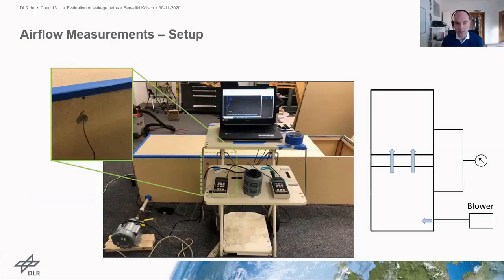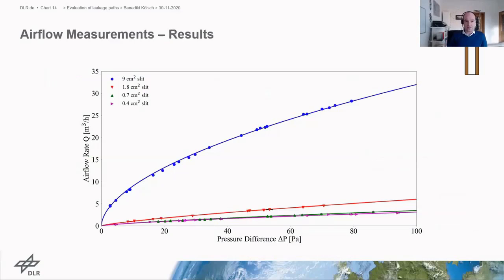And therefore, the pressure difference between these two chambers can easily be calculated between ambient conditions and the pressure in one of the chambers. I will now show you some example results of these 43 different configurations. Here, for example, is a configuration where we measured a double wall construction with 100 millimeter distance without any insulation material and a straight channel connecting these leaks.